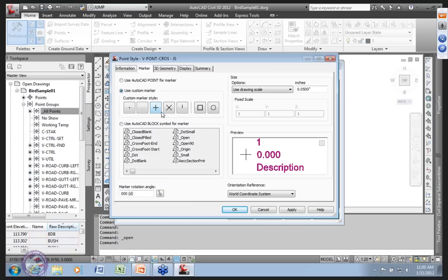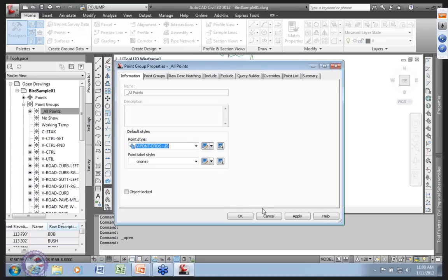Okay, we're going to leave those. So if you actually want them to be a block when they come out, then employ a style, so that after you explode, it'll end up on the right layer, determined by the description key set, and your graphics will stay together. So we got our symbols all handled.